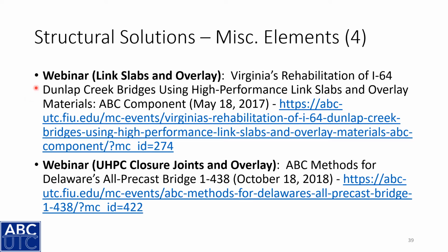The next webinar shown here has link slabs and an overlay. Link slabs are a common ABC technique, so this webinar talks more about that. And then this webinar here for a project in Delaware used all precast elements, and they used ultra high performance concrete in the closure joints. And then they also used a UHPC overlay. So it's an interesting webinar for UHPC closure joints and overlay.